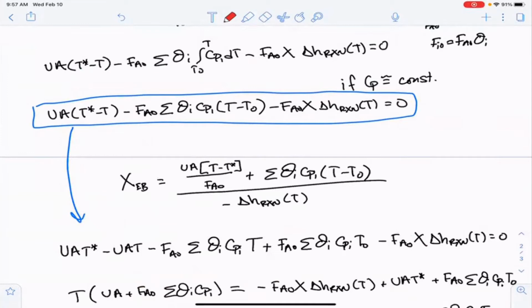Because now when the temperature changes and the compositions change, the number of mole balances we need is essentially N species, however many species are present in the reactor. And now for the temperature, we need an energy balance. In our previous example, where it was adiabatic and this term wasn't there, we could use that solution. And in this case, where there is a jacket, we will use that version of the energy balance to solve problems.